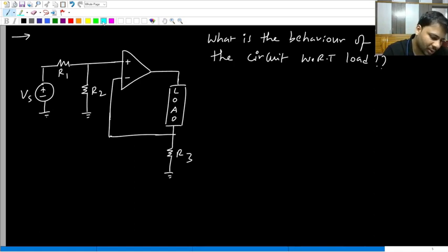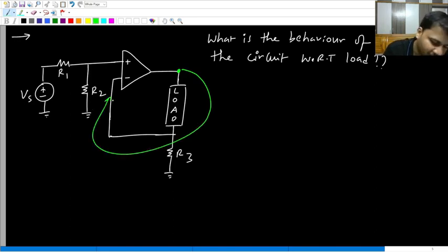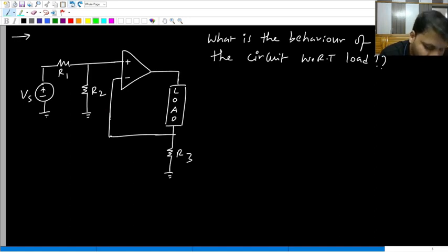Okay, anyway, please look at the screen, all of you. First, do you all agree that the op amp is in negative feedback? It is obvious, right? Because the output of the op amp is connected toward the minus input terminal only. So the op amp definitely is in negative feedback. So for an ideal op amp in negative feedback, we can use the concept of virtual short, which is V plus equal to V minus. What is this current? 0. What is this current? 0.